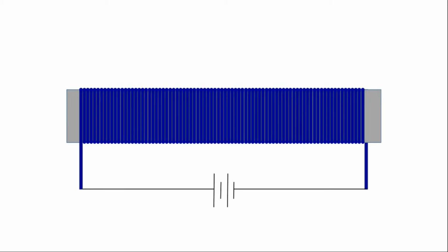So here is my electromagnet. This is the soft iron core in the middle here, and then I have wrapped it with a very thin wire that's enamel coated. Some people call it motor winding wire, or some people call it magnetic wire. When we get to the bench demo, you'll see exactly what I'm talking about here. But for this purpose, it's just wrapped around that soft iron core, and we are going to try to concentrate the magnetic field lines in that core to make an electromagnet.